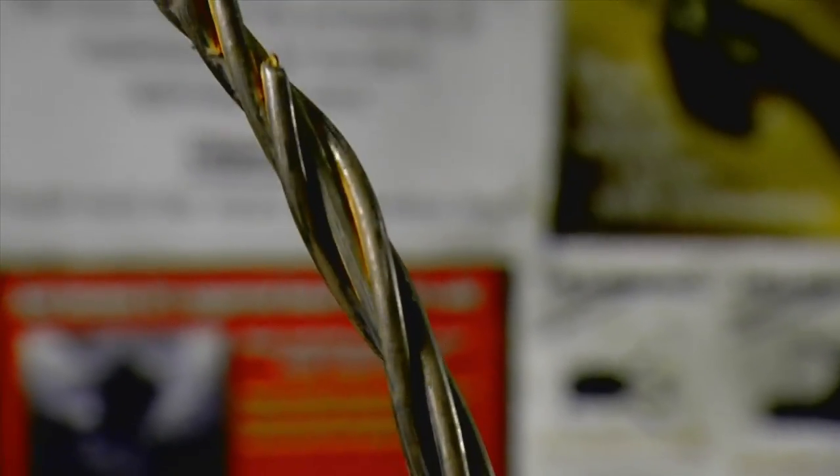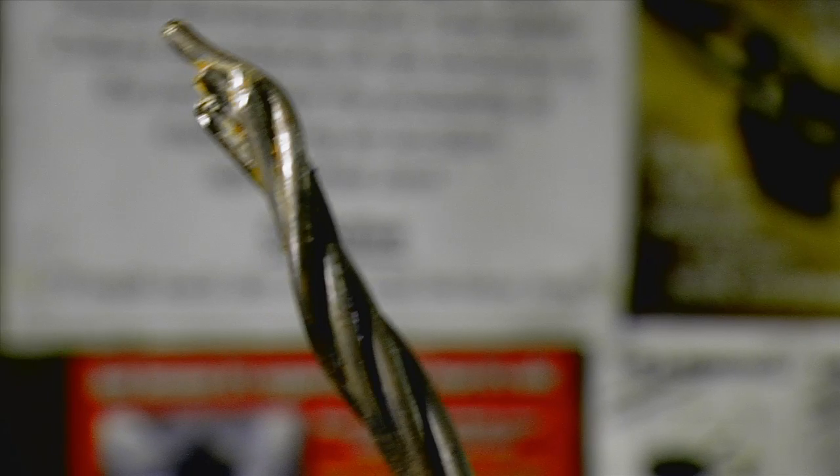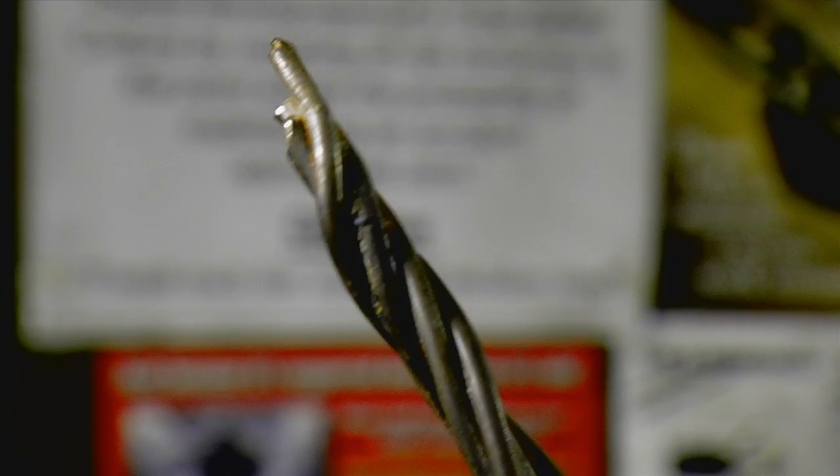But one thing Genmar will always say, you never spin a cable backwards. This is a sample of a cable bolt that has been spun backwards. A normal cable bolt is rated anywhere from 29 ton to 31 ton. We usually call it a 30-ton bolt. If we spin it backwards and it don't come together, it breaks at 5 ton, just like his sample.